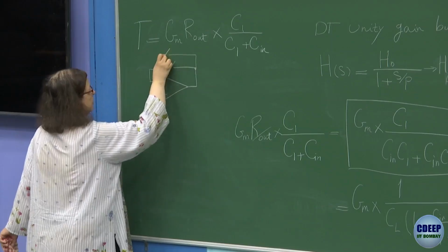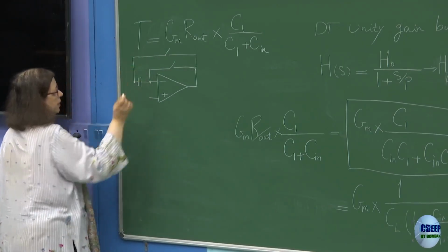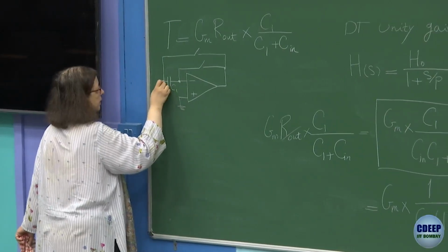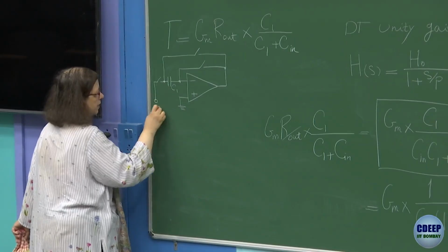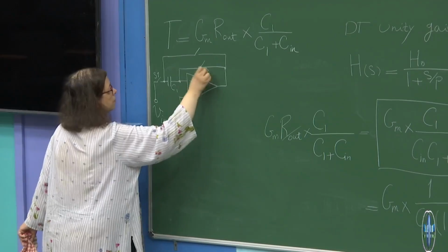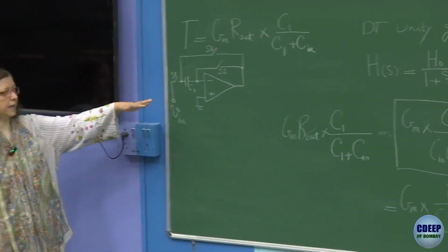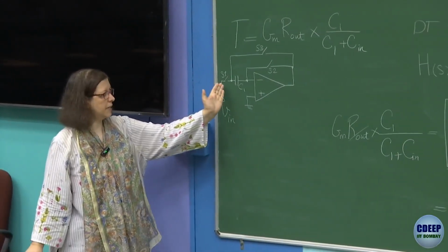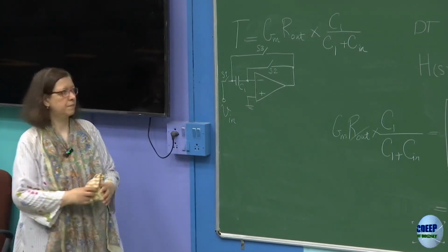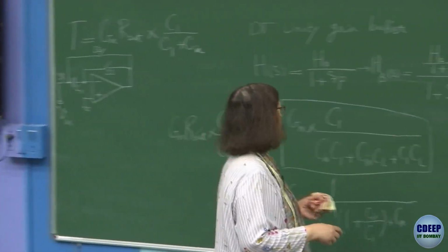There was another switch to connect the left plate of C1 to create feedback, and finally one more switch for the sampling or tracking phase: S1, S2, S3. During the buffering time, which is also the whole time, this gets flipped around the op-amp. That's why it is called a flip around buffer. That's just the name, in case you see that.